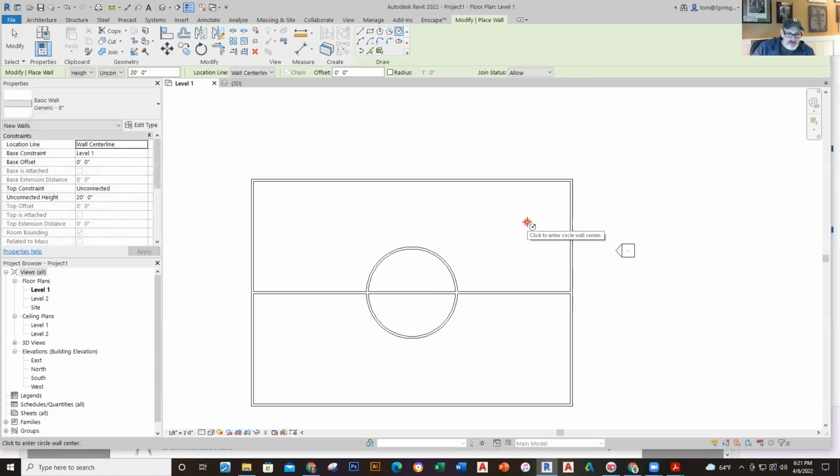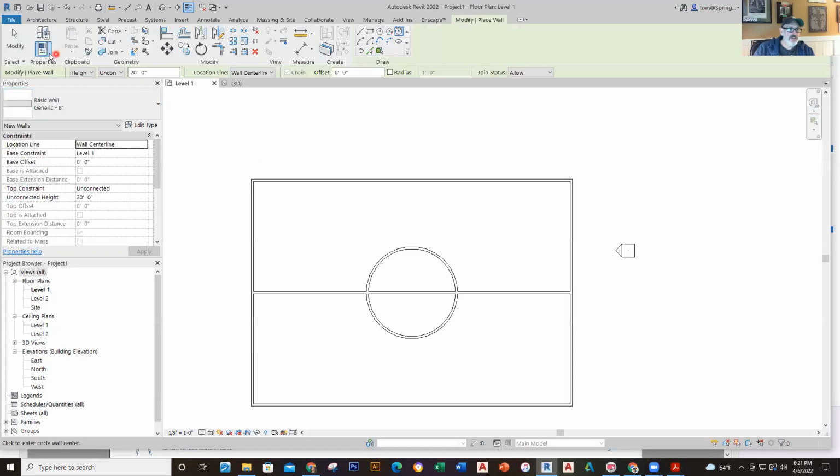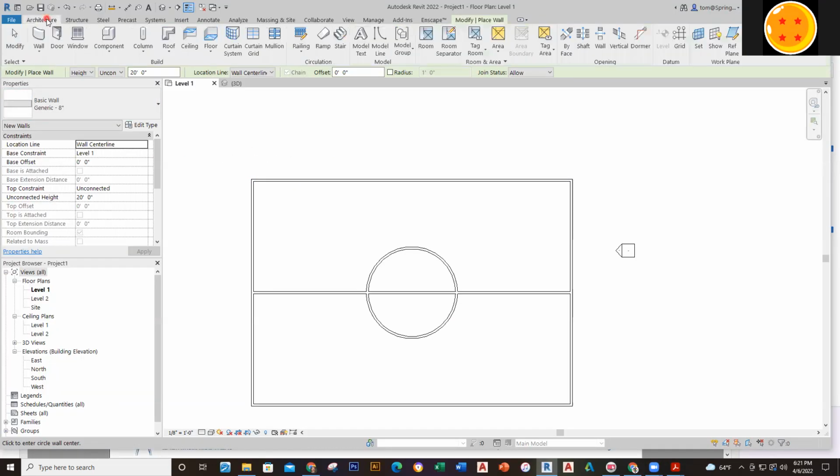And then let's see what else I'm going to do. Then I'm going to offset. I'm going to make a copy of this wall over here. I'll just make another wall that's, what, 8 feet above. Let's see here. Is that 8 feet? Yeah, it is 8 feet. So I'll go ahead and make another wall right here, 8 feet above this one. So I'll go to wall and I'll touch it here and I'll pull my cursor up. And the distance is going to be 8 feet.